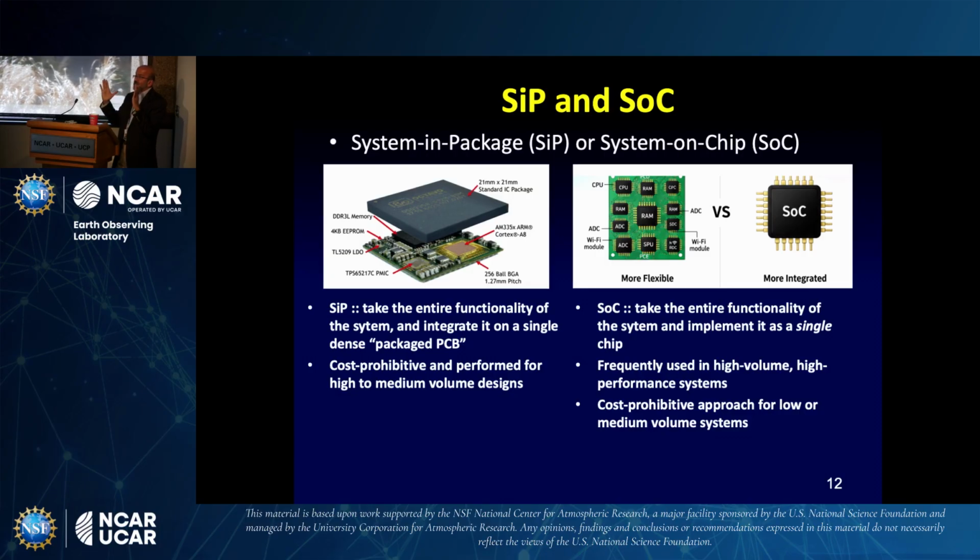So where we've been so far, we just talked about how packages have gotten better and better to where the package is about the size of the chip, the die itself. That's the best it could be, right? Now let's talk about how these have been used in systems, right? So the competing paradigm for the chiplet interposer paradigm is the system in package paradigm.